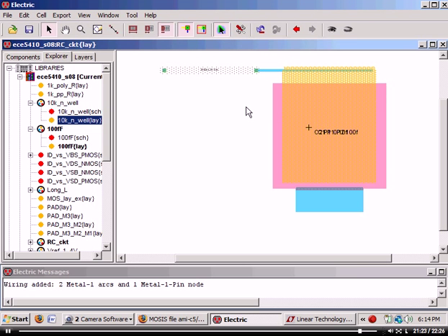Any questions? Yes? On the next assignment, you said you want to connect around our gates or pads. Just use the pad you used before. So 75 micron pad. Yeah. So you're going to have this little bitty layout and then a huge big number of pads. And then the body's going to be connected to a pad because you have to have it so you can do the body effect. If we were making 12 pads, I think I remember you saying that minimum size pad would be somewhere, and that depends on the process.